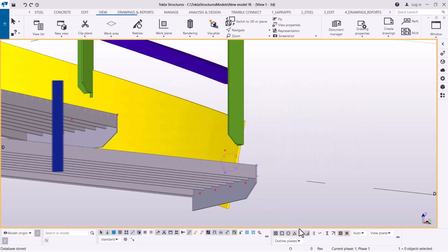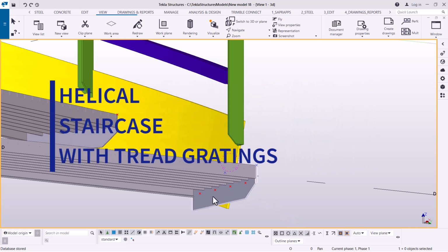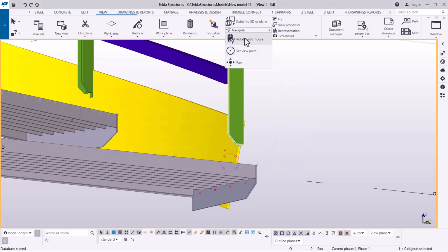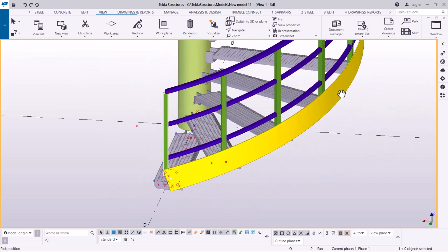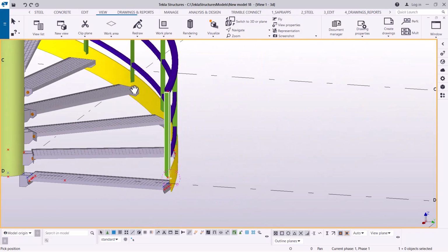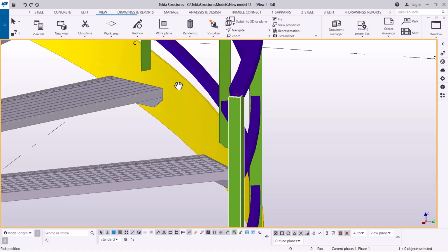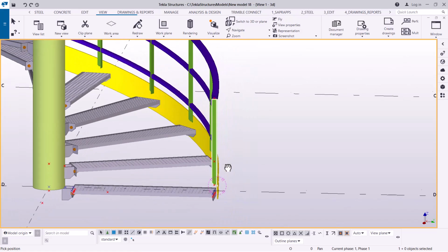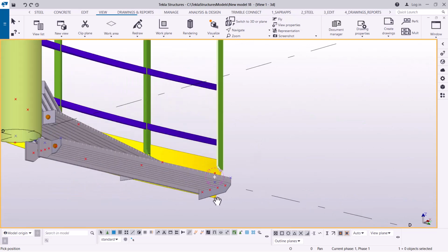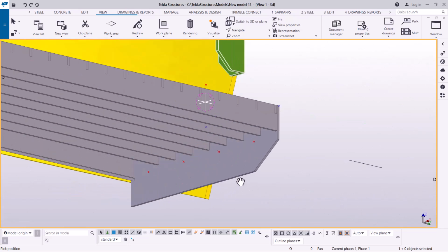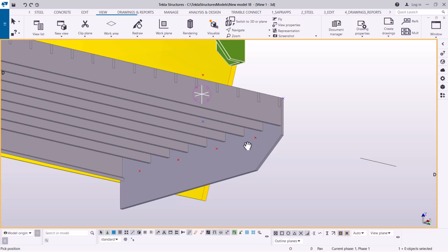And this time round, we are going to bolt the thread to the stringer, the spiral stringer. You see this. This is the stringer, and we have the threads framing into the stringer. So how do we connect them to the stringer is by bolting. So to create bolt position, first of all, you have to mark points like I have created here.